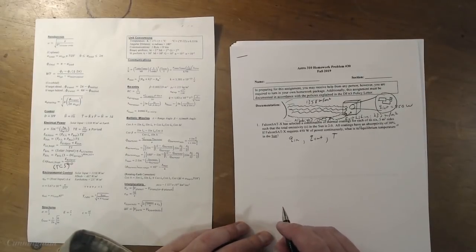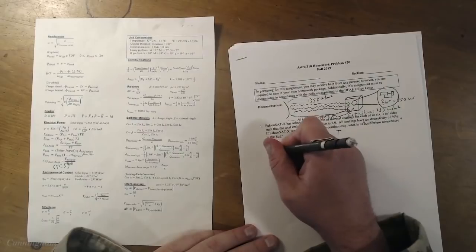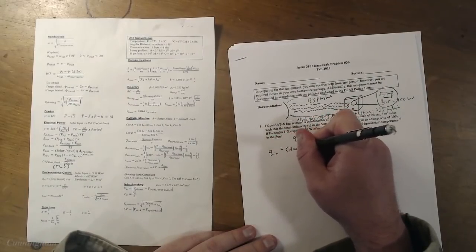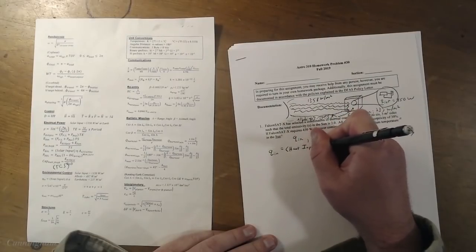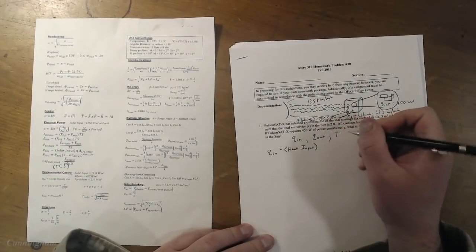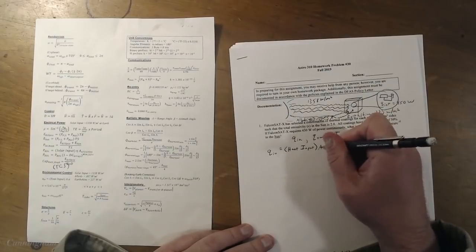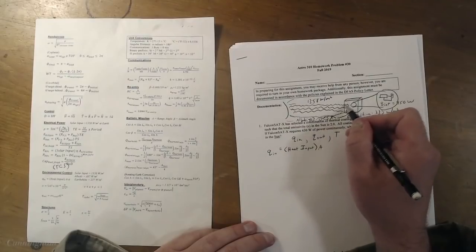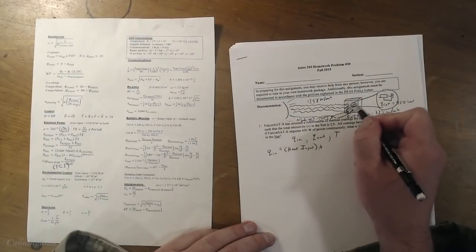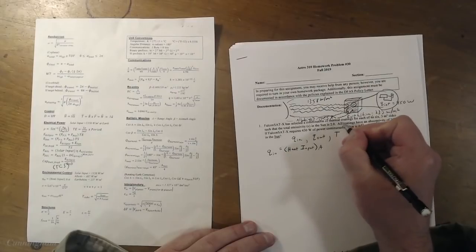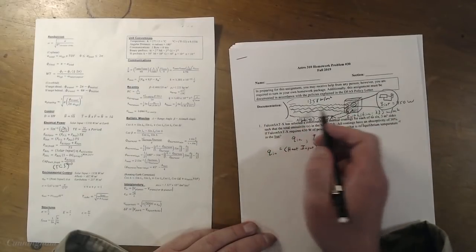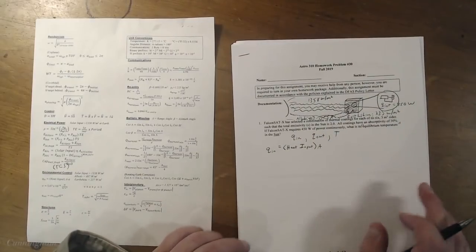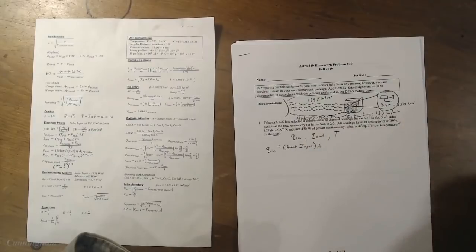Okay, let's see. I'm just going to write the Q in equation. The total amount of heat going into this satellite equals the heat input, which I'm going to show you in a second, times the area of the side of the spacecraft that's taking all this heat. We're going to assume it's coming into the spacecraft on one side. Or you could say the Earthshine is coming from below, the sunshine is coming from one side, and the albedo is hitting another side. Doesn't matter. You're just going to assume that all the heat sources are hitting one side of the satellite.